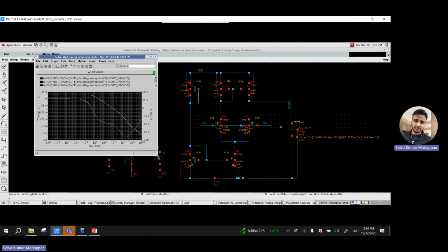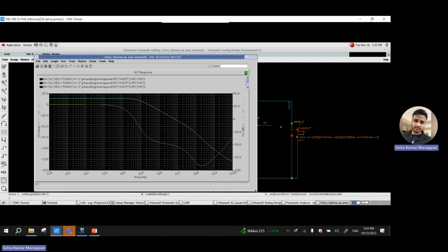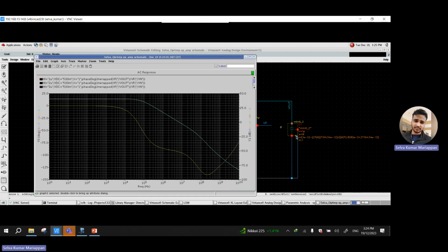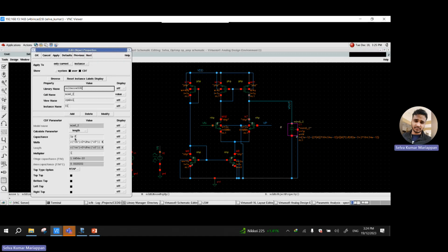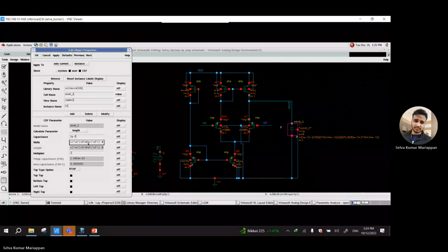Okay, so seems like the output is not much impact on your circuit. So you can just select your 1 picofarad as your capacitor. Seems like there's no heavy impact on your output capacitance value. So once you change that, not much changes on it. So you can remain it. Okay, it saves you much more time. Whether you are setting it 1 pico or you are setting it up to 20 pico, it's not going to change anything.